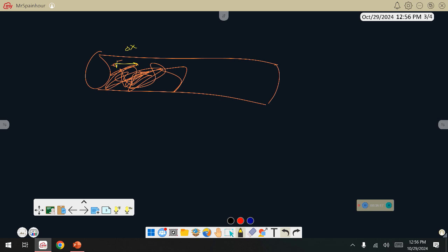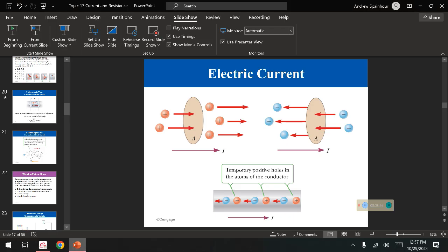Even though we said that for a copper wire it was moving at 1 millimeter per hour, we were moving 10 coulombs per second. How can we be moving so much charge? Well, there's a lot of charge jam-packed into running through that particular area right there. Does that make sense? If it will, think of it like this: imagine a traffic jam with 20,000 lanes. Does the traffic jam have to be moving quickly to move a lot of cars past a particular point? No, it doesn't.